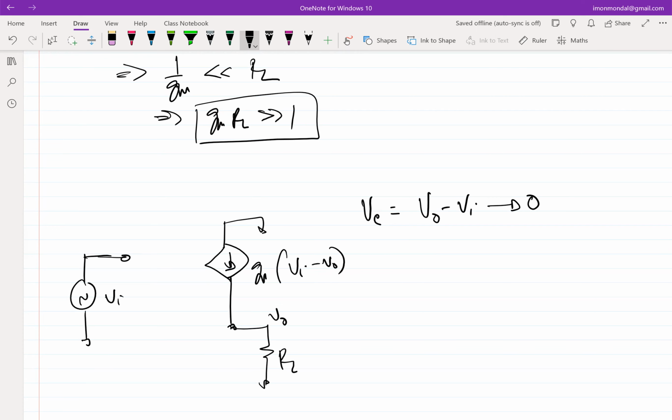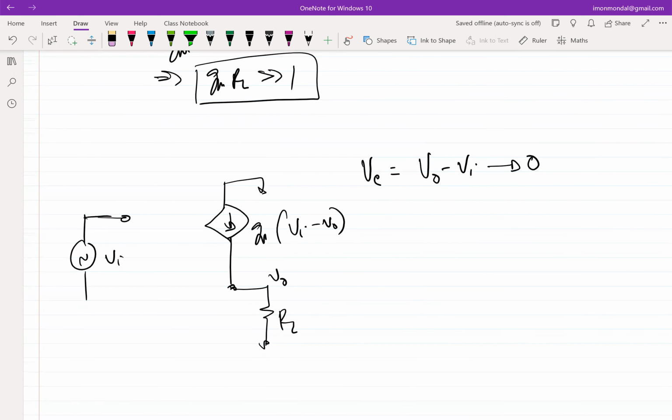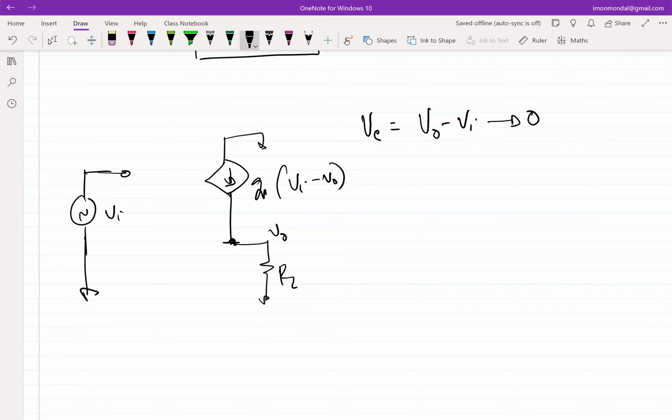Now that after this, we did some mathematical analysis, but we didn't revisit whether this is indeed in negative feedback or not. So let me spend a couple of minutes to delve into this. So now let me take a cue from the question that he asked. Let's assume that this Vi increased, right? This Vi suddenly increased. And let's put a small capacitor CP to impose some semblance of time, right? If there is no capacitor, everything is instantaneous.